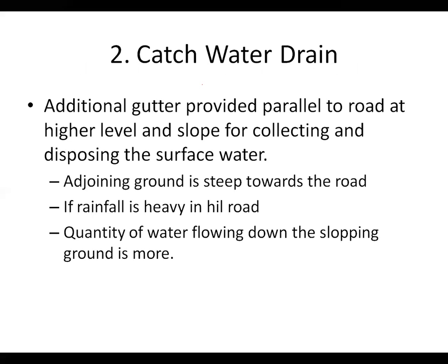Okay, wherever you go, the simplest way of providing highway drainage is providing a side gutter, so in different forms you cannot deny the presence of side gutters. In many highways side gutters are provided, but side gutters are effective when the road is on an embankment and the other portion is at a lower level.